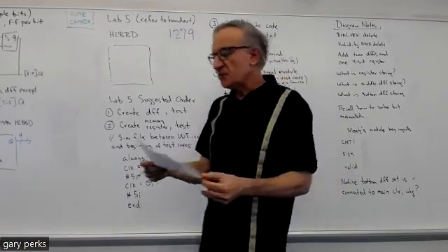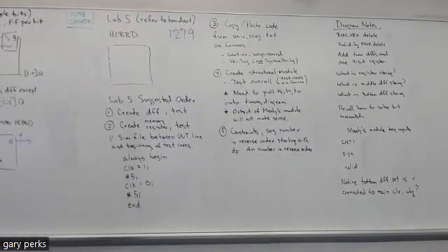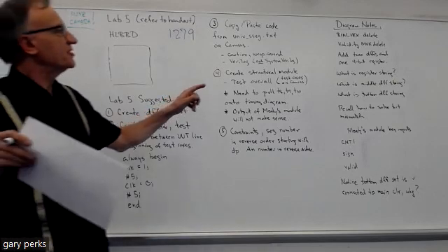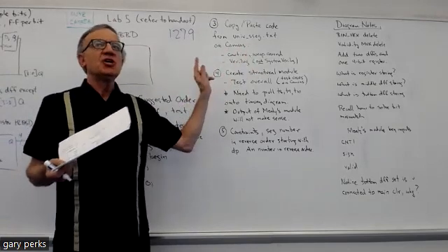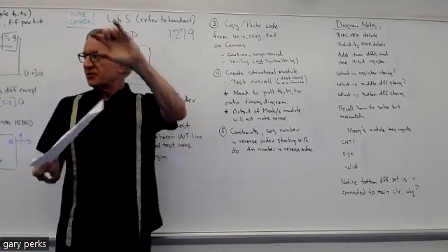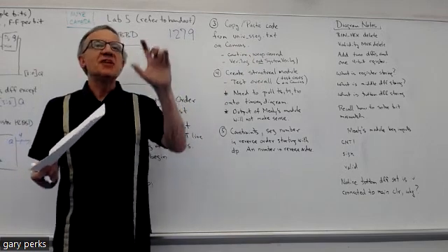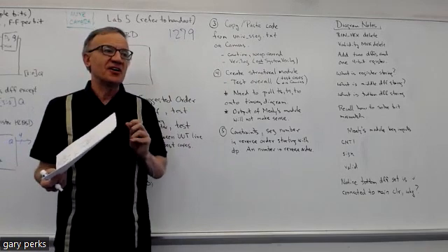Okay, and the reason we give you this code is because if you take a look at it, we give you the code in a text file, not the actual file, and you have to copy and paste that code into a design source file. And Dr. Mealy, he wrote this in Verilog, okay, instead of System Verilog. So that's one of the things you got to watch out for: when you go to copy and paste the code from the text file, when you're creating your design sources, make sure to choose Verilog and not System Verilog.